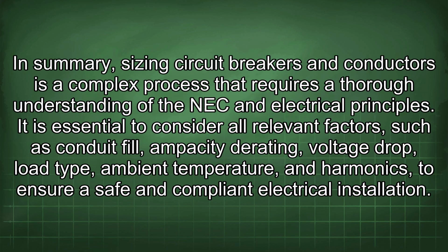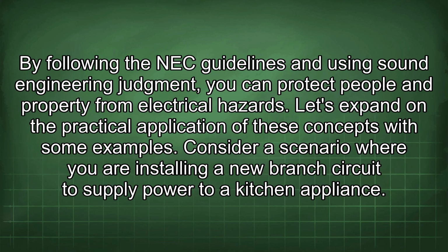In summary, sizing circuit breakers and conductors is a complex process that requires a thorough understanding of the NEC and electrical principles. It is essential to consider all relevant factors, such as conduit fill, ampacity derating, voltage drop, load type, ambient temperature, and harmonics, to ensure a safe and compliant electrical installation. By following the NEC guidelines and using sound engineering judgment, you can protect people and property from electrical hazards.